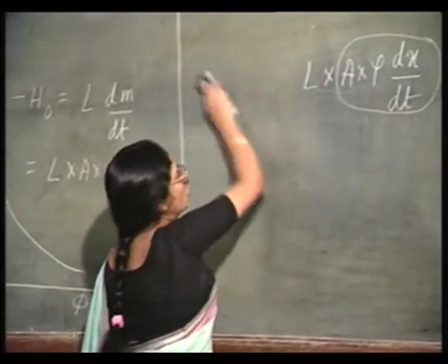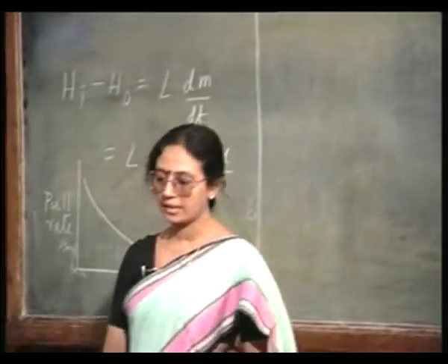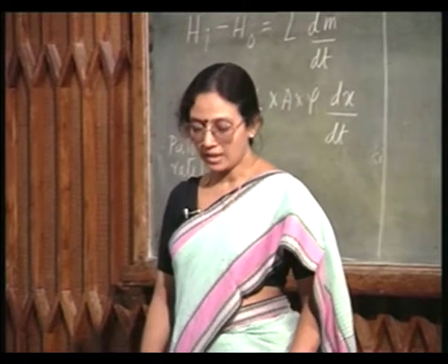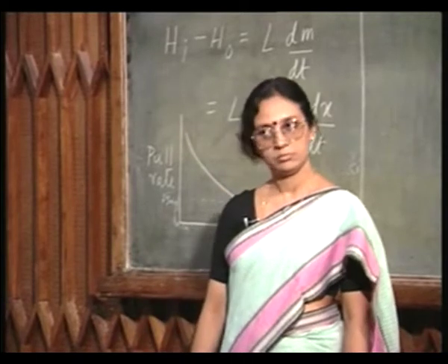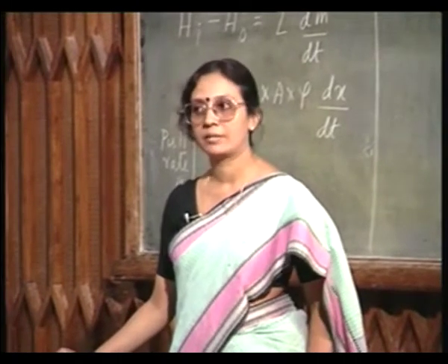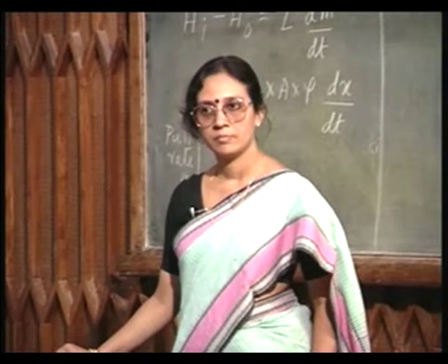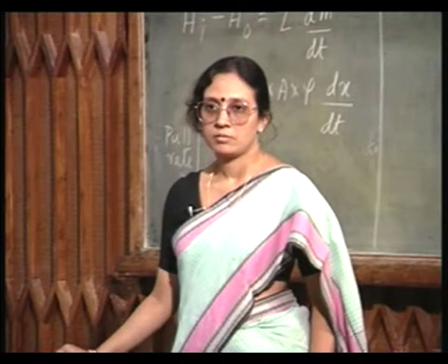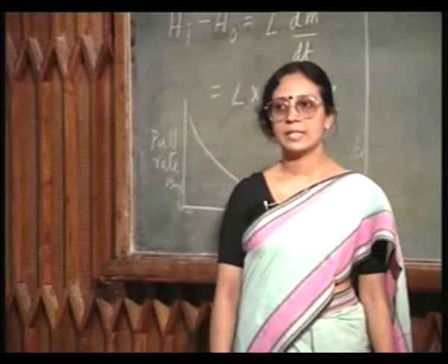The dopant incorporation during crystal growth is actually a very interesting thing. You see, any impurity will have a solid solubility in the crystal, and it will also have an equilibrium solubility in the melt, and these two are not necessarily the same. It has a different solubility in the crystal and in the melt.